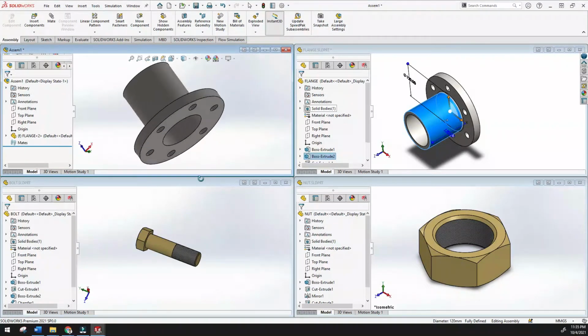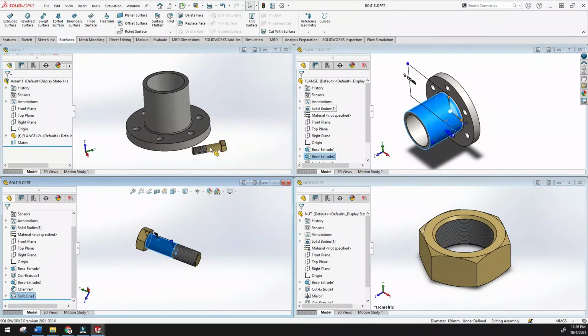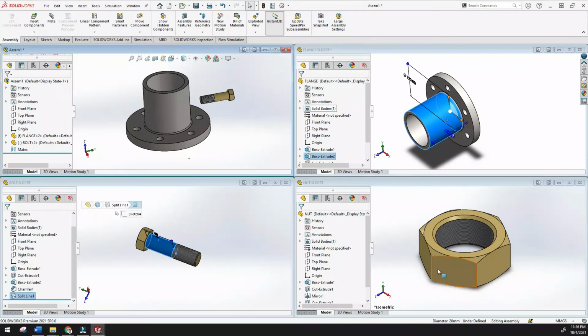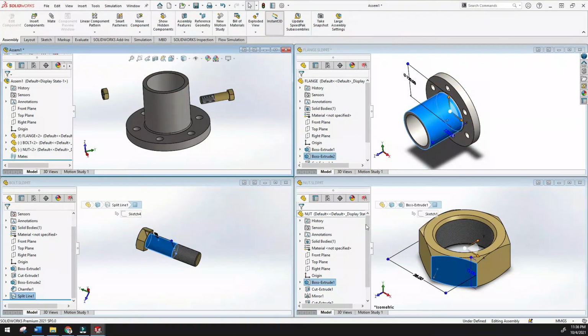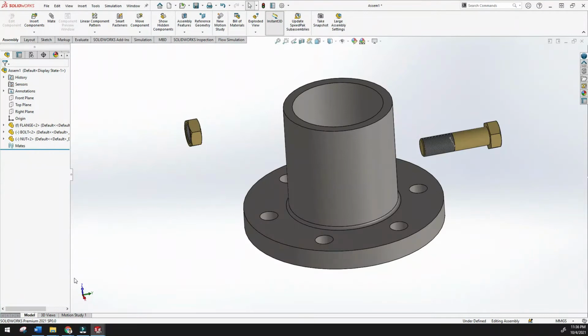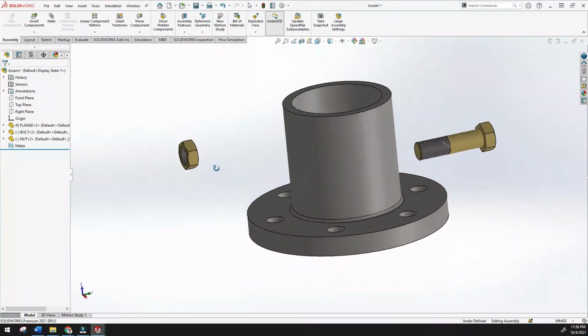Again, just click and drag to the assembly page, no need to use the Control button, okay. Again, just click and drag to the assembly interface, that's it. And no need to close this one, just make this one bigger like this, okay. Automatically all will be hidden. Now this is the second way to import the parts, okay.